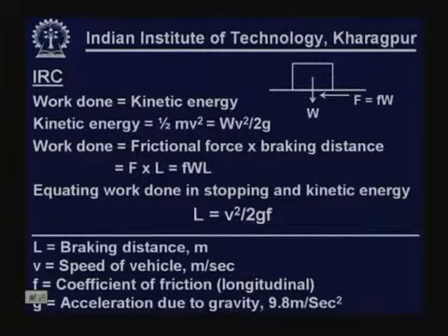This is the basic equation used by the Indian Roads Congress and also by AASHTO. However, IRC uses the coefficient of friction for calculation of stopping sight distance.